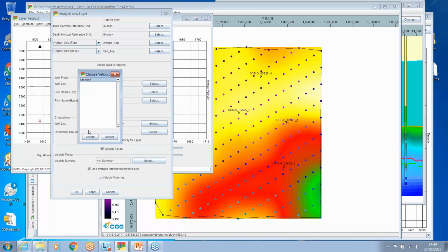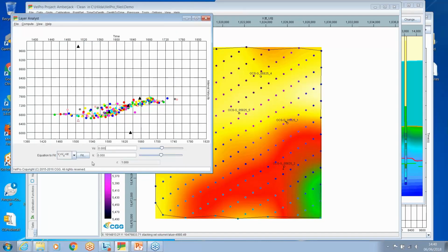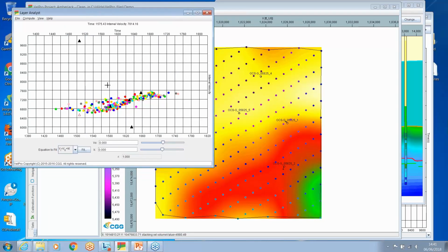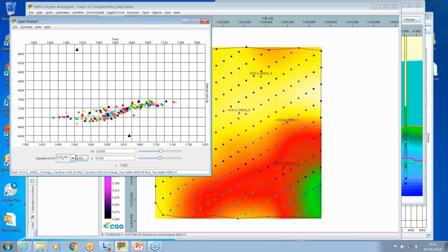The velocities. Okay, and then in this example, we can see that we have a couple of well outliers. With mouse button 2, it gives me the name of this well. In this case, it's number 2, and this is number 3. Those are a couple of wells that I have to check what happened with the check shot of the well peaks. Something is wrong there.